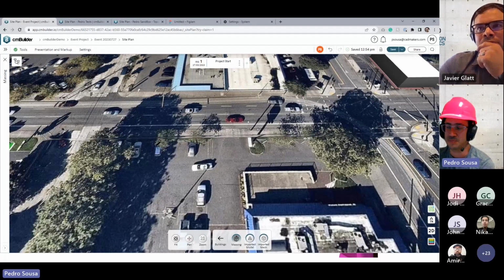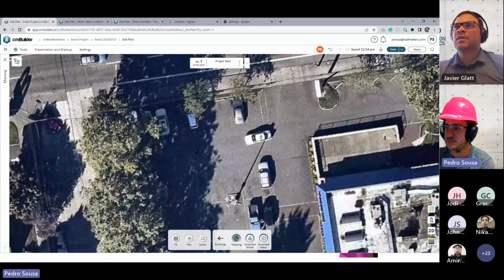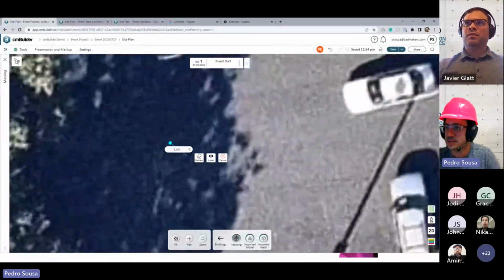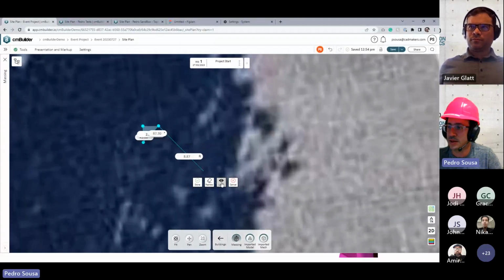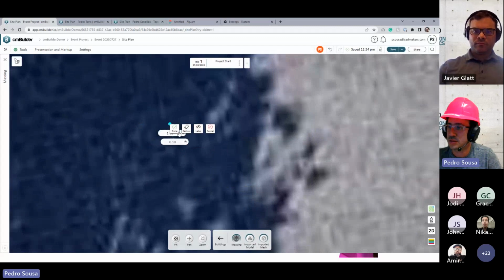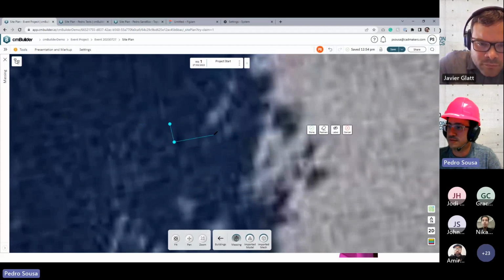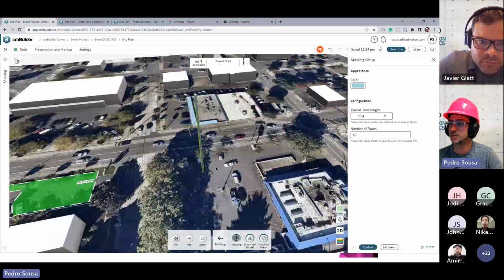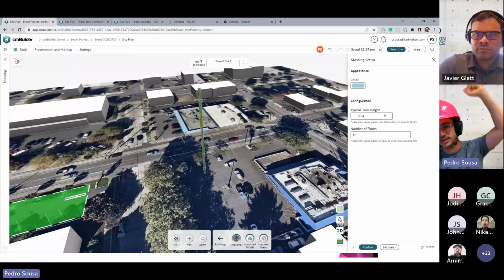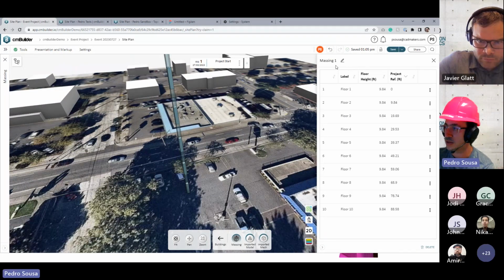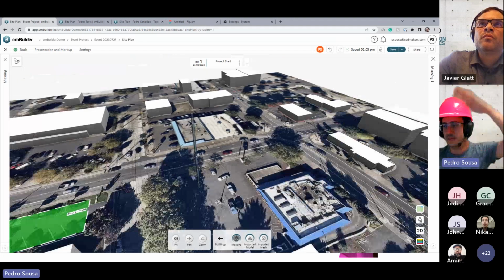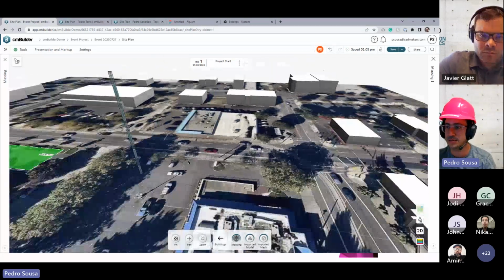Because then, depending on how high your building is, it's better for you to create several detail masses, because then you can just go in and define, sorry, let me redraw this. So you can define the different heights for it, right? Because you will create a repeating setup of masses, and then you can use that. You can name this in the name of the column that you want. But basically, for columns that you want to show a bunch of them, that would be my suggestion.